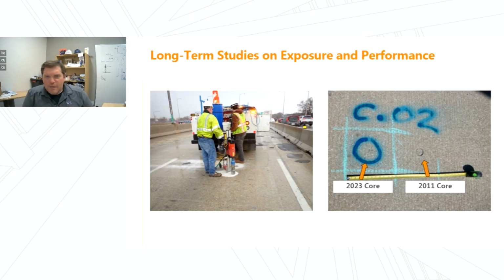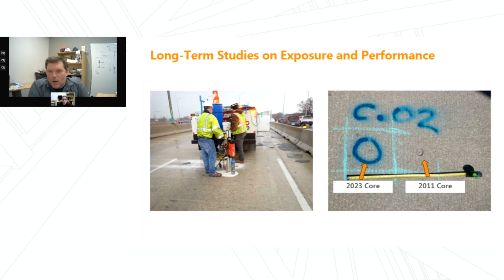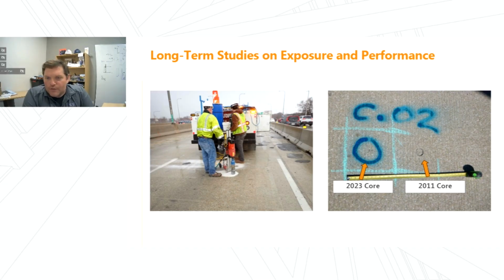Another item that's come up in our work is how these bridges perform long-term, both exposure as well as performance of these bridges over time in service. So in 2023, we went back to a series of structures that we had pretty detailed chloride data on, and wound up collecting additional core samples and evaluating changes in the chloride exposure as well as changes in the chloride diffusion characteristics.